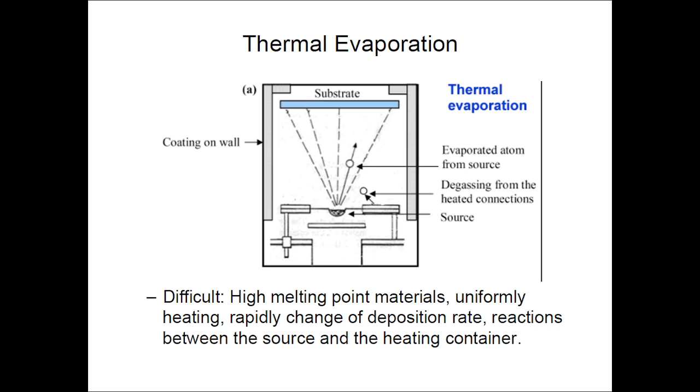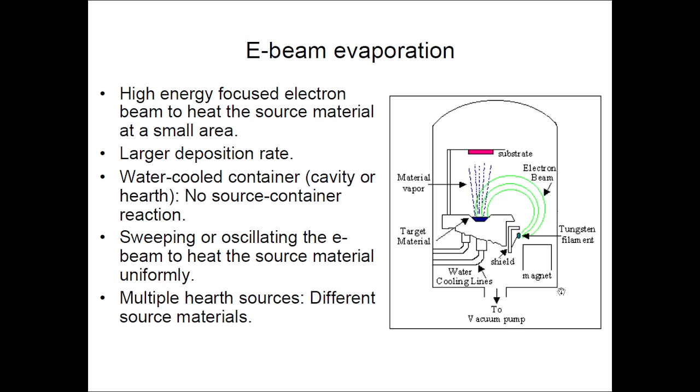Okay, and we need to execute uniform heating, otherwise the deposition rate and yield will be different. So the temperature has an important role. The temperature should be raised steadily for heating purposes. So that is what you need to focus on in thermal evaporation.